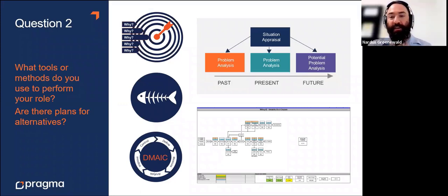Johan, this is again a great summary of tools and some of the very basic ones that we use all the way through to the more mature tools. Again, maturity comes up. I think the 5 whys is the very, very basic one that you need to instill at every single company. That's your artisan level troubleshooting type tool that you really need to at least be the champion for. Be the guy that goes through the breakdown job cards, and if there's not a 5 whys filled in, say, listen, we need some more information here.